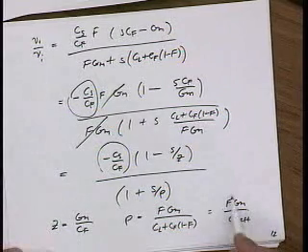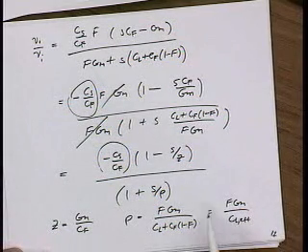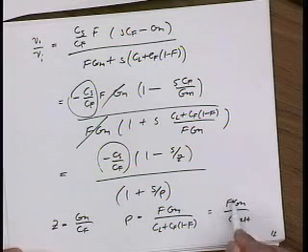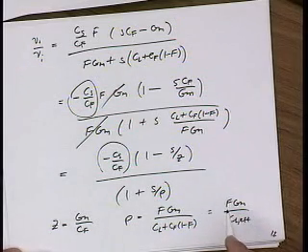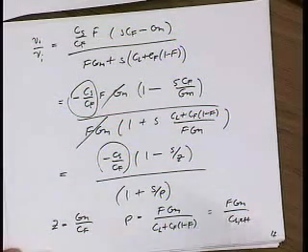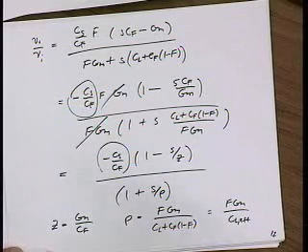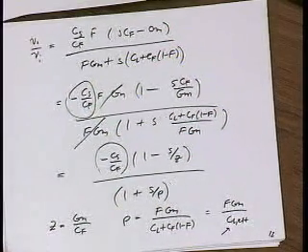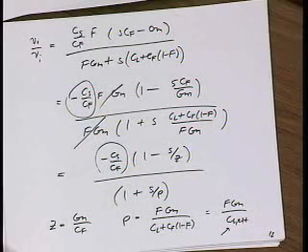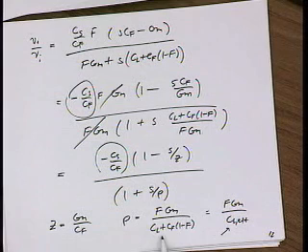So I'm applying feedback here so that my gain, instead of being what it is for the amplifier, is 1 over F, and so my bandwidth should improve by exactly 1 over F, which is F. So the bandwidth is F times the unity gain bandwidth. How about CL effective? Does this make sense? Anybody want to comment on the form of CL effective? Why isn't it just CL?